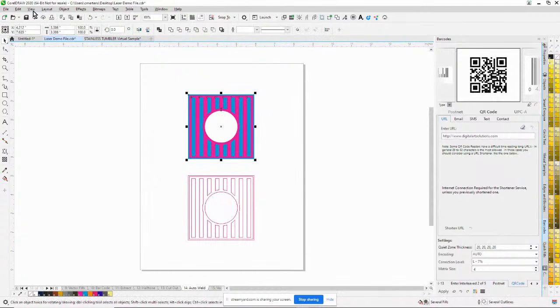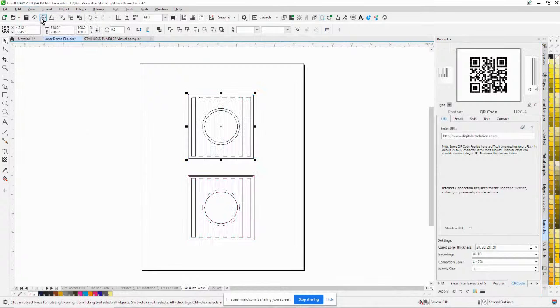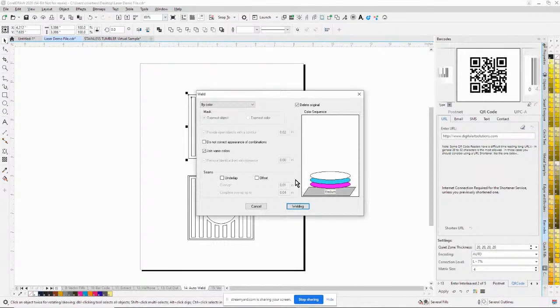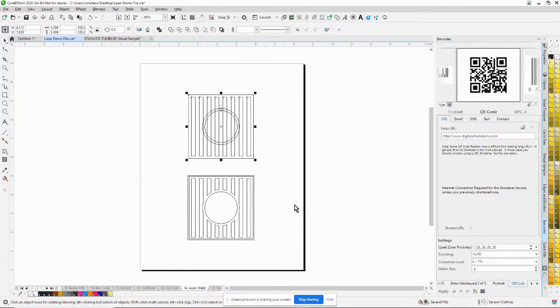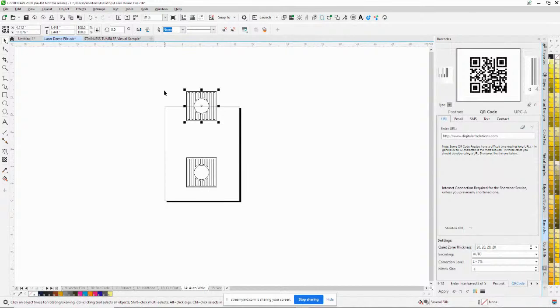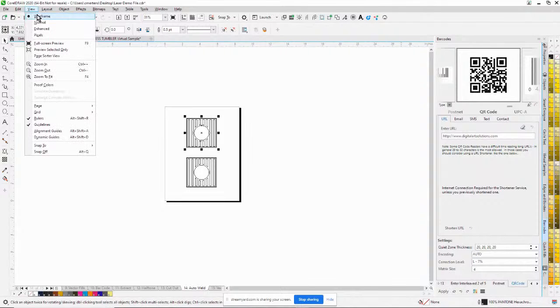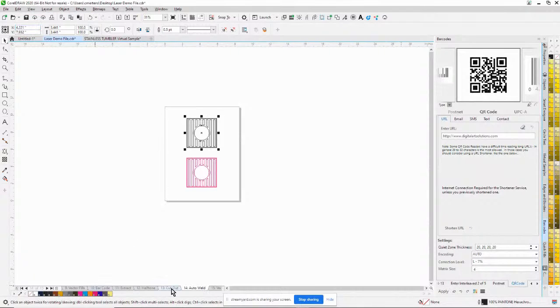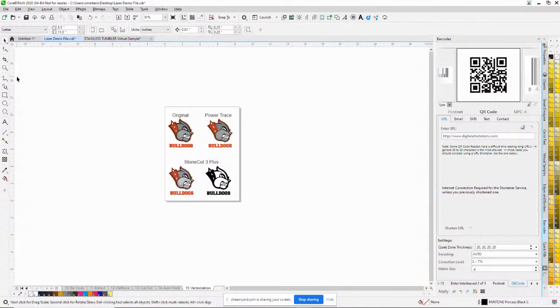Getting this file set up for production in our system is a one-click deal. I would just go to auto weld and use the auto weld function to set that file up, and then I would recolor it down to black and white. So I'd get rid of the fill, give it an outline, and you're set up there. And last but not least, we're famous for our vectorization.